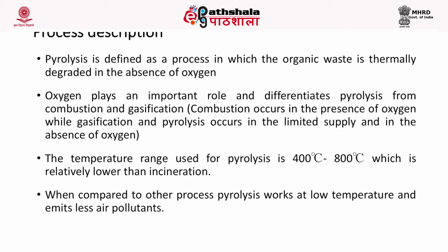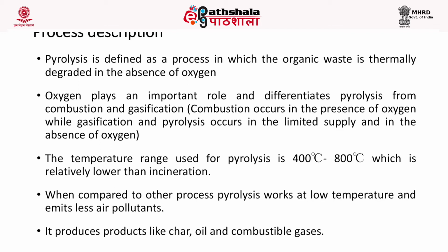I'm sure you know what combustion is. Combustion is nothing but burning something in the presence of oxygen. And gasification or pyrolysis is degrading or burning the waste in the absence or a limited supply of oxygen. The temperature used is generally between 400 to 800 degrees Celsius, which is comparatively lower than incineration.